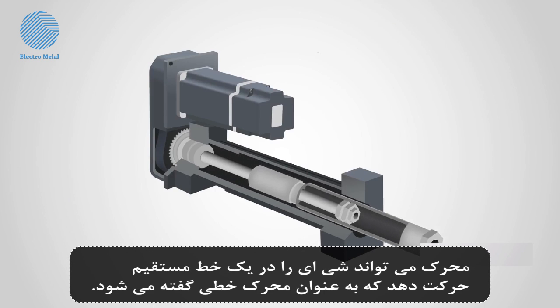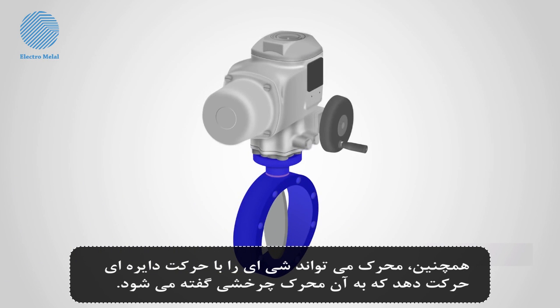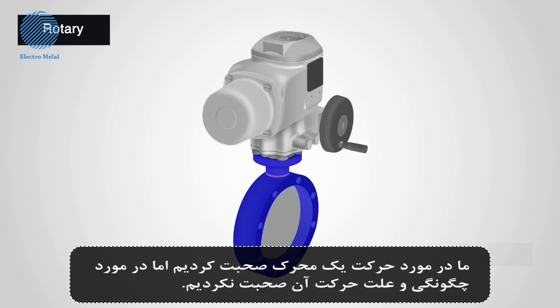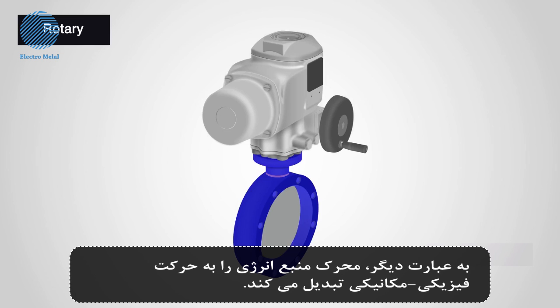An actuator can move something in a straight line, also referred to as linear. Also, an actuator can make something move in a circular motion, also referred to as rotary. We've talked about the movement of an actuator, but we haven't discussed how or what makes it move. An actuator receives a source of energy and uses it to move something. To put it another way, the actuator converts a source of energy into a physical mechanical motion.